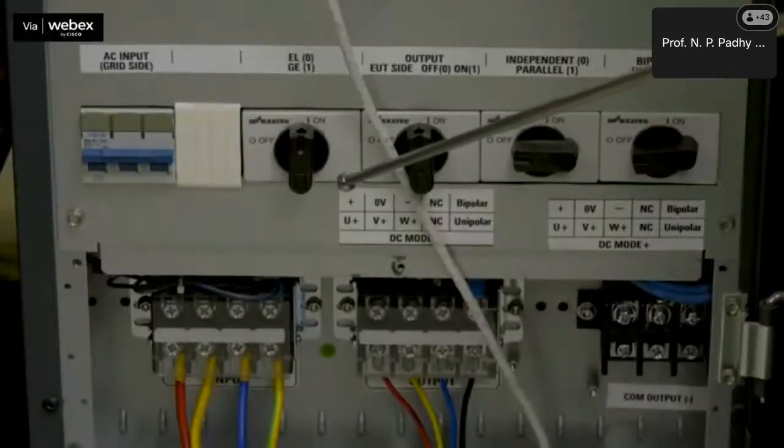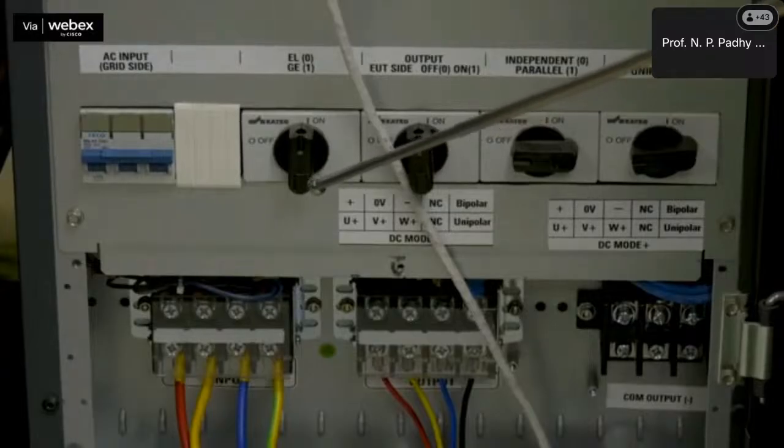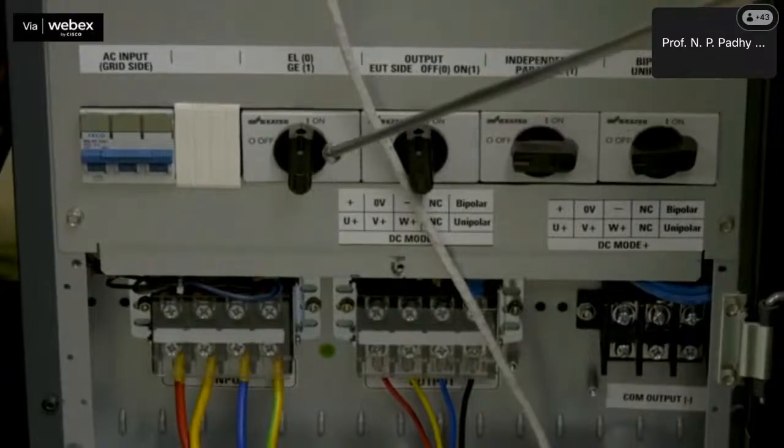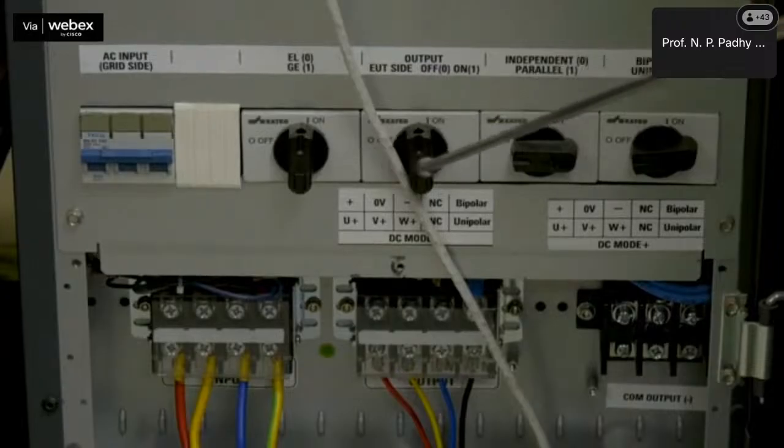If the working mode switch is at AC mode, the equipment can be used as an electronic load and grid emulator. Similarly, if the working mode switch is at DC, the equipment can be used as a DC source, battery emulator, PV emulator as well as programmable DC loads. The various functions of this equipment are configured with these 4 switches from left to right. The switches are numbered from 1 to 4. Let us see how to configure various functions of this device.